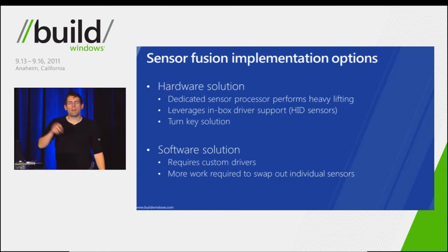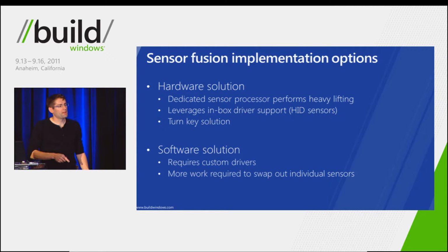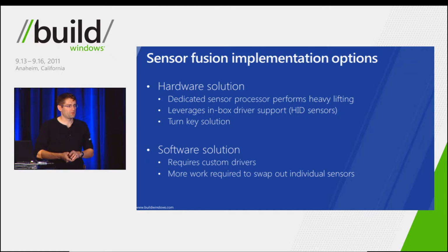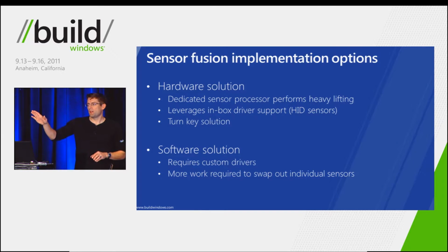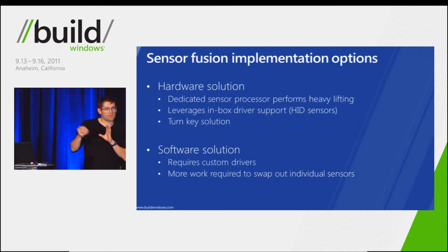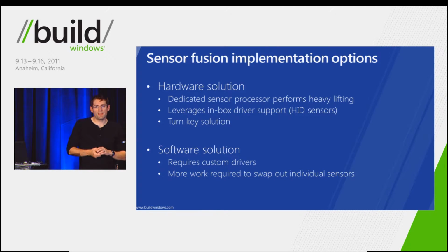So, how do you support sensor fusion in hardware? We're really advocating two different approaches to integrating the sensor fusion technology at the system level. The first is the hardware-based solution. That's actually the approach that was taken with the Samsung Windows Developer Preview device. There is a dedicated sensor processor on board. The dedicated sensor processor supports the HID sensor profile. It also has slave sensors that it interacts with to get data and to implement the fusion algorithms.